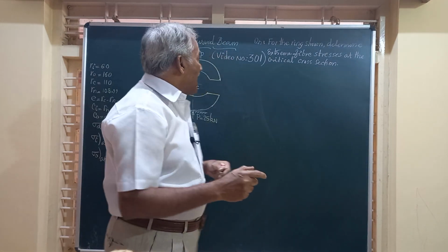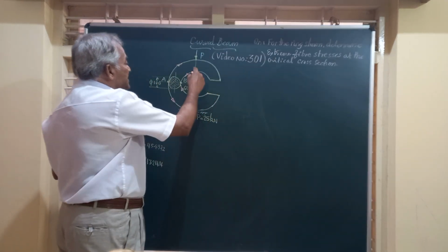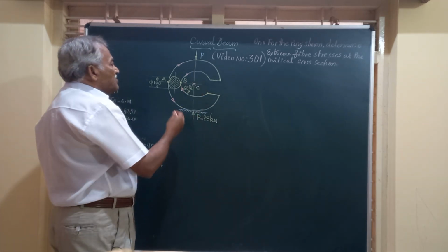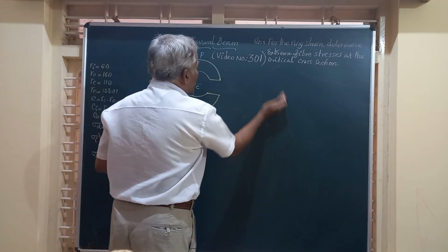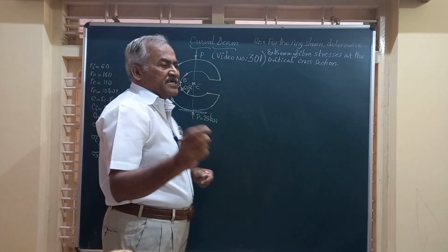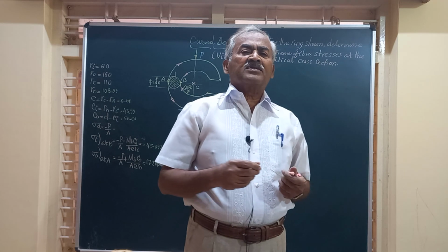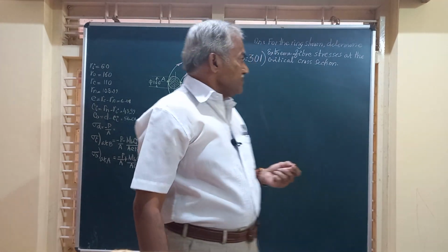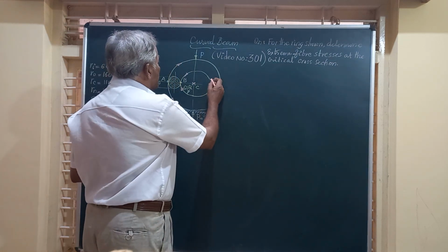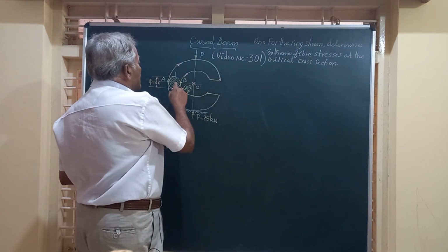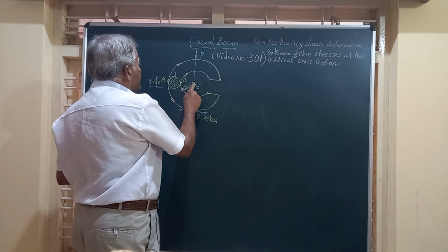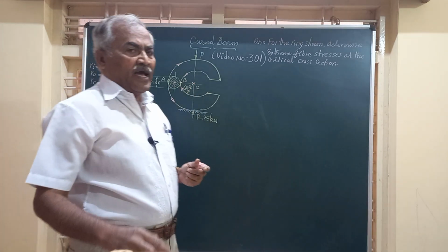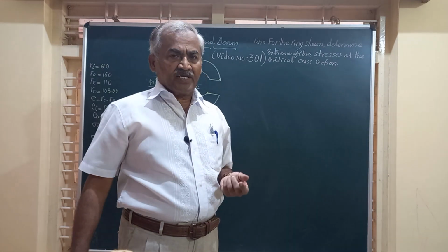So friends, and then when you come to this eccentricity, when you see the center of curvature here, friends, we have to find out what are the stresses. Number one is the direct stress. The second is the secondary stress. Friends, here what happens, because of this distance between center of curvature and centroid of the figure, we have a bending stress.